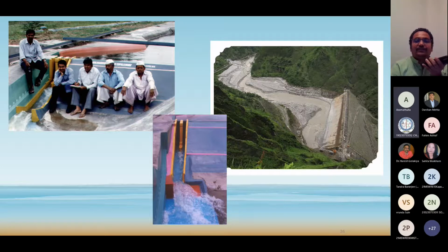This photo, you can also see the upstream here. My boss suggested that some problem would happen at that time, and it happened, you know. But in this one, I worked on a high head structure, all rigid. Another division, the flood control division, will put a mobile bed and sand to release and manage reservoir capacity. But I considered only the spillway capacity, the velocities and pressures, and also reproduced scour with a bed model using mobile bed material.